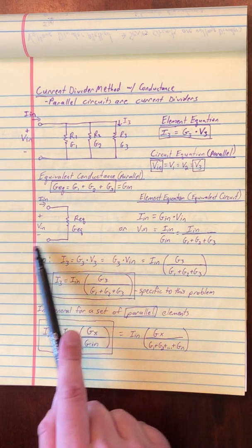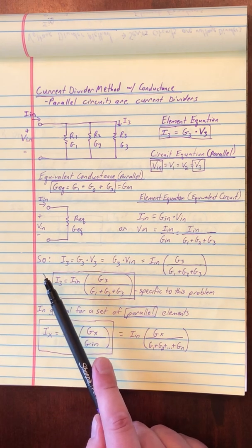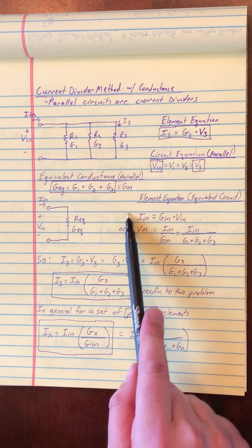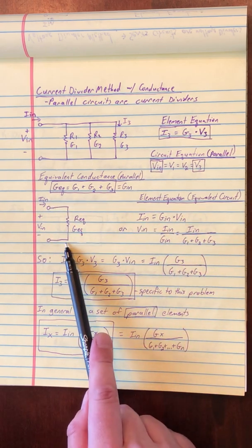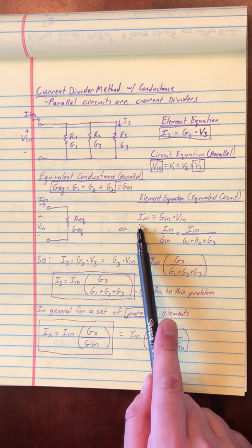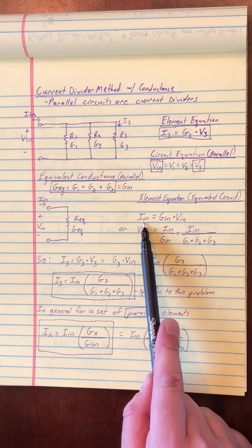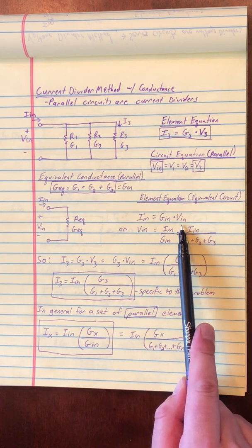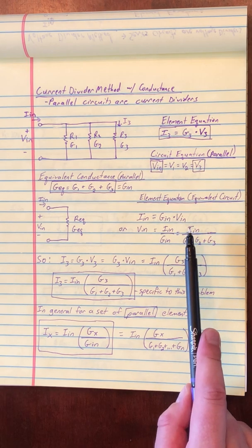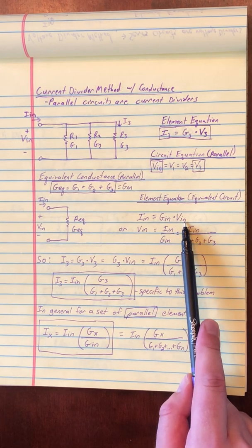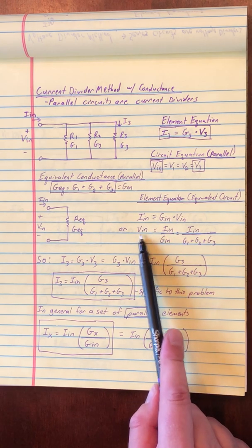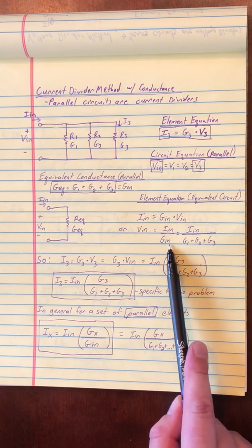And then we have something similar to what we did for the voltage divider rule, except now we're looking at conductances here. So I can write the equation for this simplified equivalent circuit in terms of the conductance Ohm's law. The input current is equal to the input conductance multiplied by the input voltage. Since we're going to want to substitute in for Vn so that we end up with In, I'm going to rearrange this so that voltage in is equal to In over Gn.